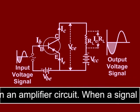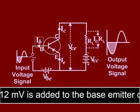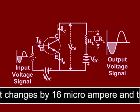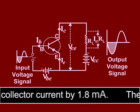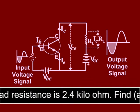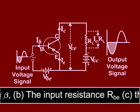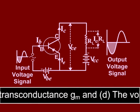In our next problem of today, a transistor is used in a common emitter mode in an amplifier circuit. When a signal of 12 millivolt is added to the base emitter circuit, the base current changes by 16 microampere and the collector current by 1.8 milliampere. The load resistance is 2.4 kilo ohm. Find A, the current gain beta, B, the input resistance RBE, C, the transconductance GM, and D, the voltage gain AV.